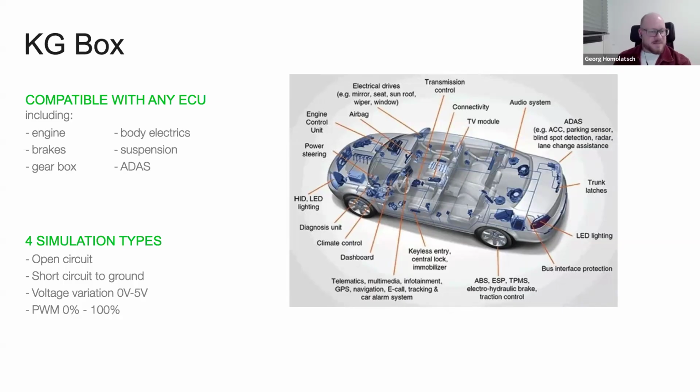All right. So with the KG box, you have four types of fault actions available, and you can set these fault actions on each pin of the ECU.